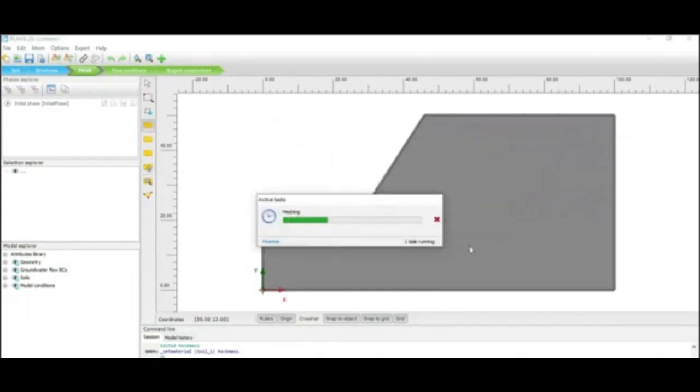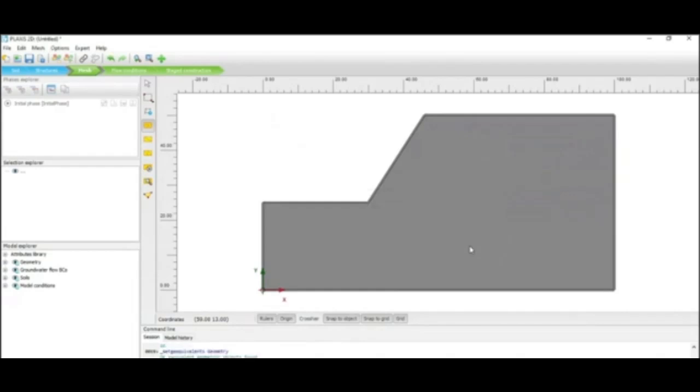So the sensitivity or the convergence study needs to be carried out. That is something which is very necessary for all the analysis. But right now I'm just demonstrating it with a very fine mesh. So let us see that once I'm using a very fine mesh, it says right at the bottom that we have generated 933 elements and there are 7,600 plus nodes in this model.